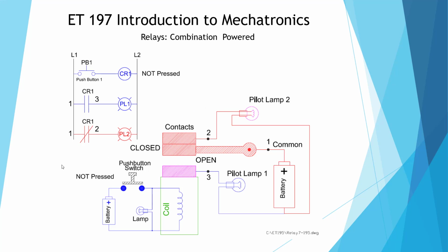So this is a ladder diagram that we'll be using, and this relay is used in logic. Typically logic relays are lower current than a relay that would be used to drive a motor or something. So we'll use logic, usually lower voltage, and then we'll have another set of relays to drive the heavy duty high current machinery.